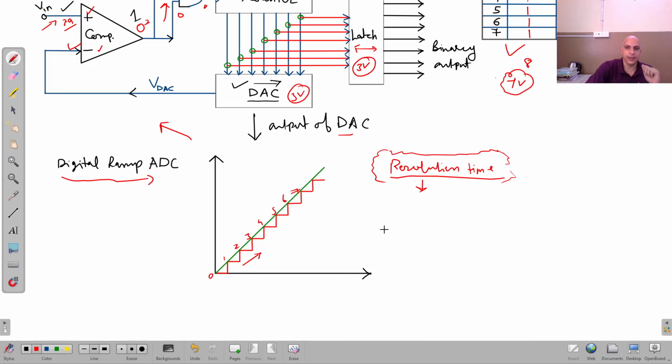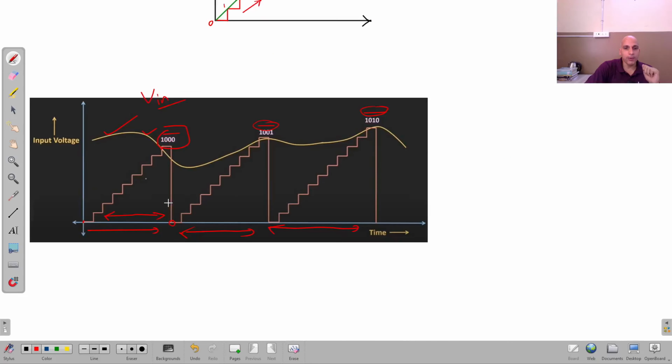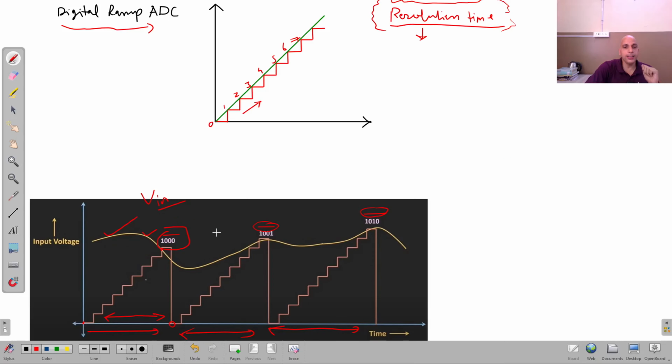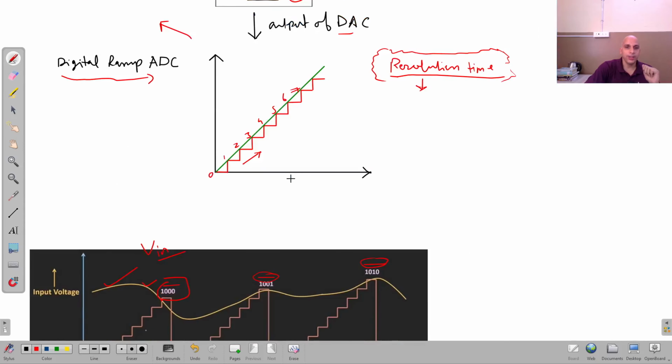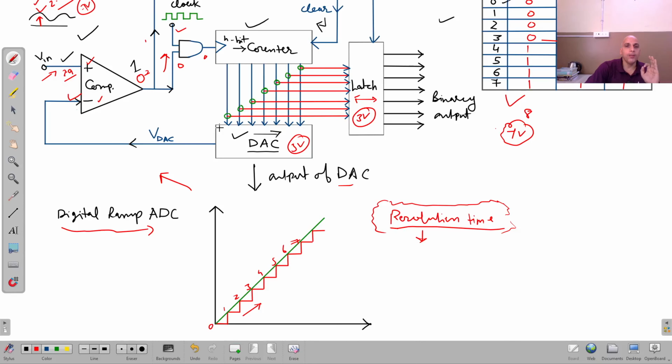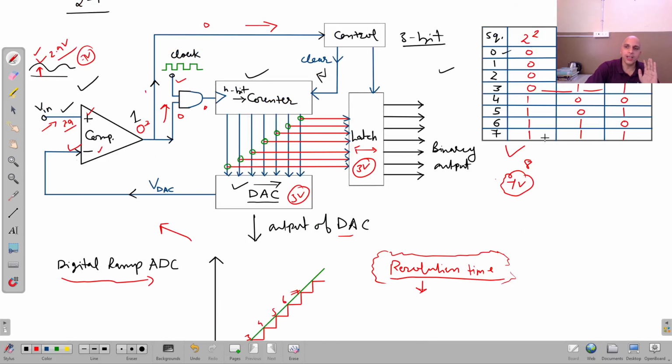And how can we calculate that time? Now as I told you, the time of conversion depends upon this sequence, because every time the counter will begin from 0. Now if we are using 3 bits, right, then when it begins from 0, what is the maximum time that the counter can take? The maximum time, which I call the worst time, will happen when this has the maximum value, 7 volt, because 7 volt is the last. If I am taking 111 as 7 volt, 7 volt is the last or maximum value that corresponds to 111. So this is the maximum value, right?